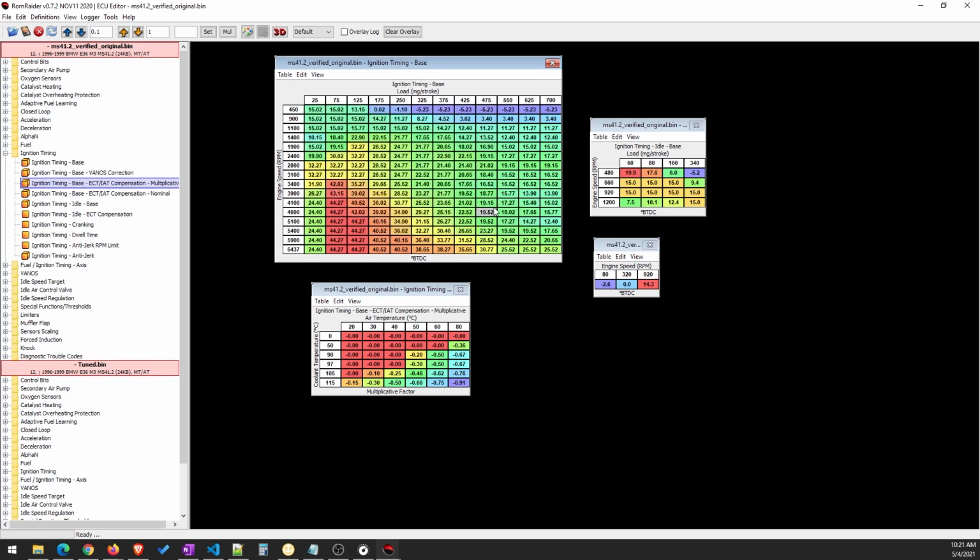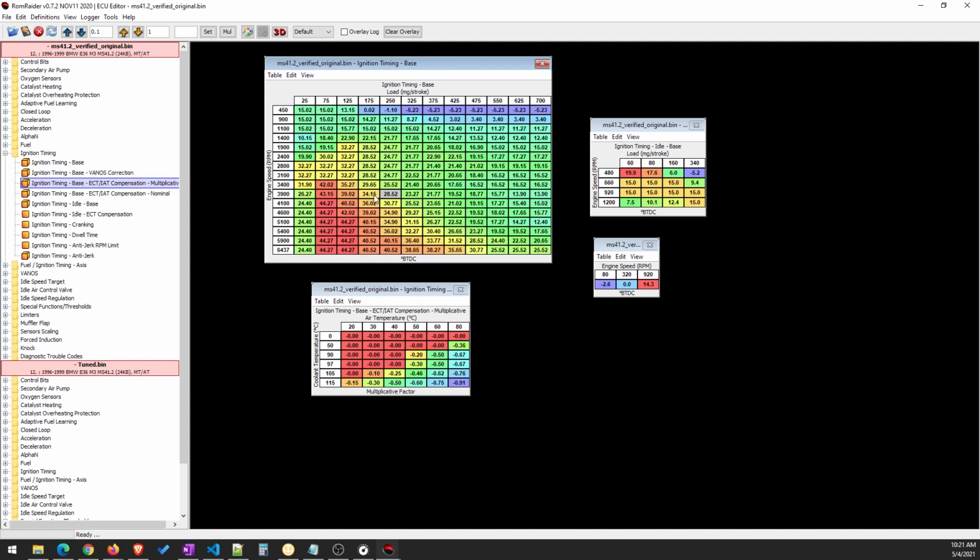Here, the main thing is you really want to run on a dyno to get your ignition table dialed in, because you may not run into any knock when you add enough timing, but you may not make peak power at those numbers. So there is a decreasing benefit if you do add too much timing.